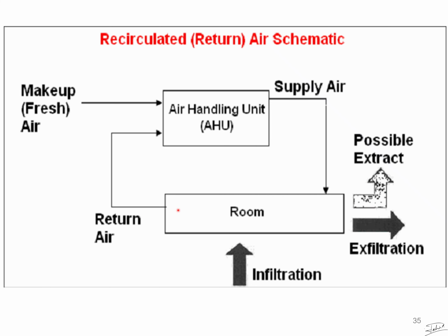Okay, and to send it back into the atmosphere would not be very cost effective. So if we can reuse this conditioned air, then it would ultimately decrease our overall cost and energy for filtering that air. So that's why return air or recirculated air HVAC system is commonly used in our manufacturing area.